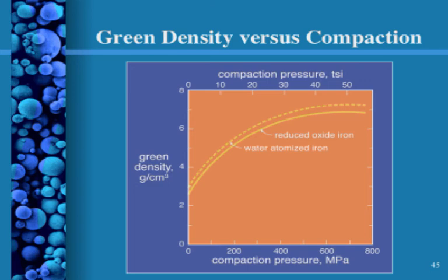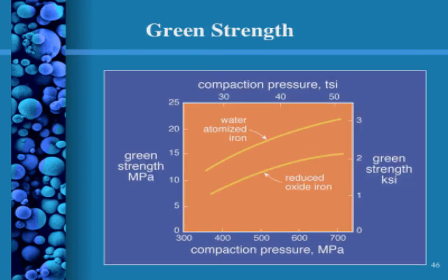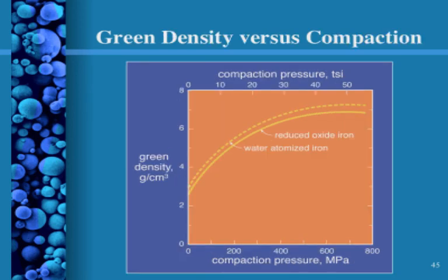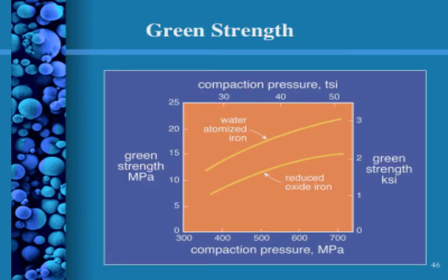But also, if I change the powder shape based on powder synthesis conditions or the powder size, the final density of the part that I'm going to make is going to change a little bit. The porosity of the part is going to change. Sometimes you want high porosity, sometimes you want low porosity. Here's an example where you made the parts at different densities and now want to look at the strength of that part, so strength as a function of compaction pressure.